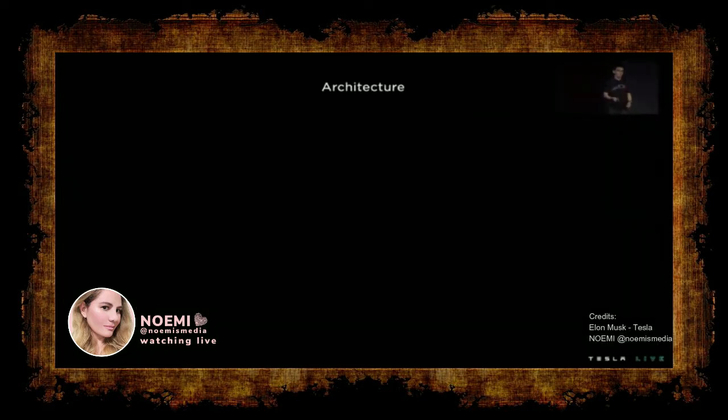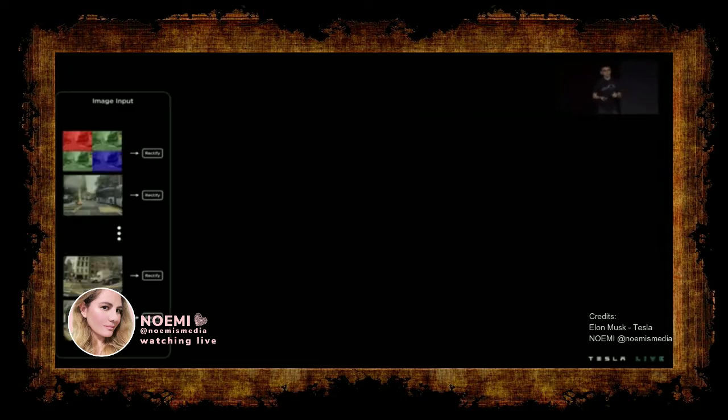So how does this work? Let's take a look at the architecture. First, we rectify each camera image with the camera calibration. And the images we're showing here were given to the network. It's actually not the typical 8-bit RGB image. As you can see from the first image on top, we're giving the 12-bit raw photon count image to the network. Since it has 4 bits more information, it has 16 times better dynamic range, as well as reduced latency, since we don't have to run ISP in the loop anymore.